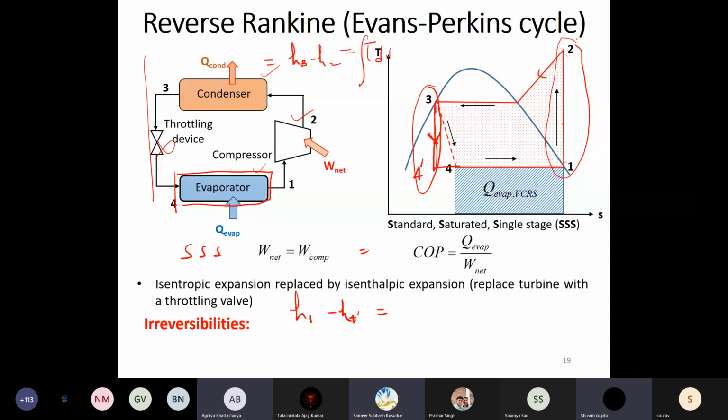Yes. Okay. So again, it is a practical call that we have taken, that in order to extract that 10% work from a turbine, first we have to place another rotating device in line with your compressor. You will incur more additional capital investment initially. You will have some maintenance of that additional turbine that you are operating. You can have failures for that also.